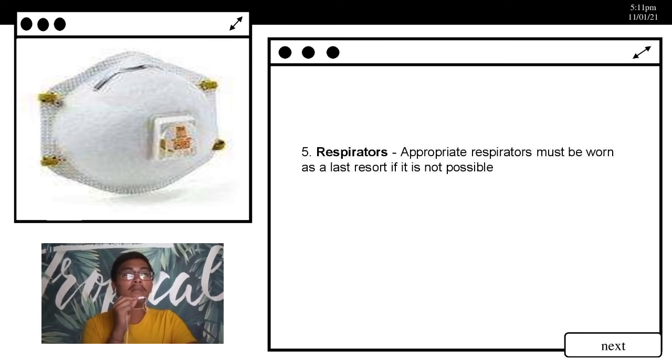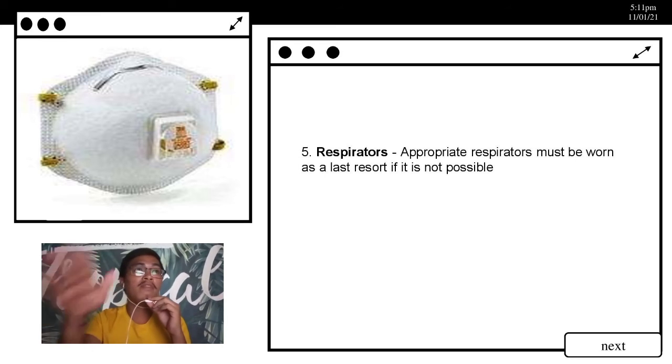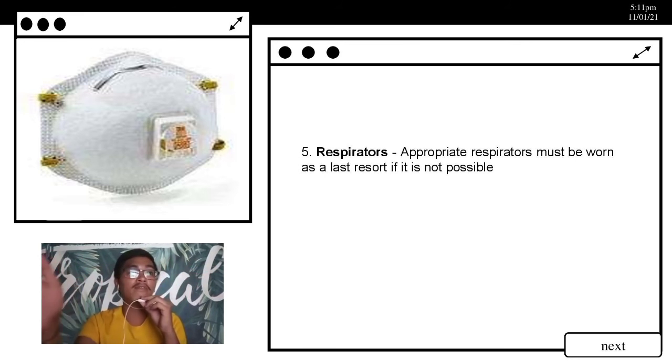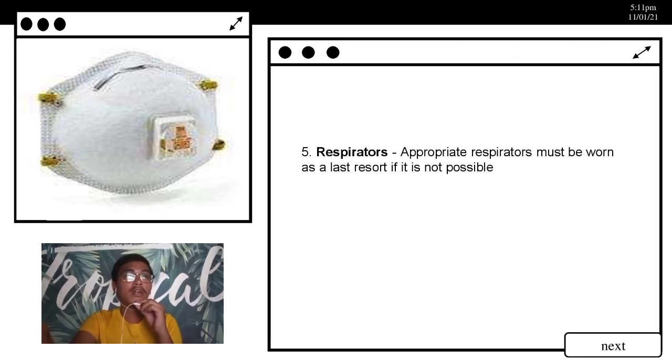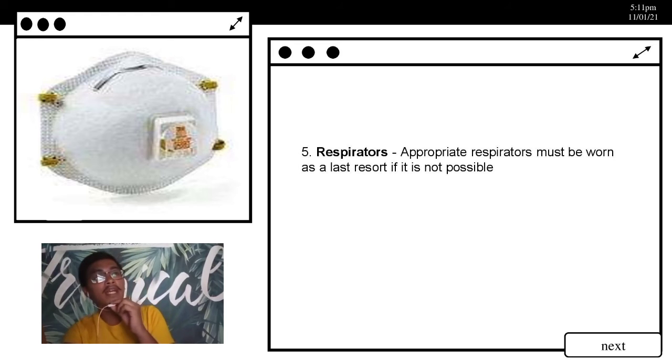You cannot use this without the half mask respirators or the full face respirators. So you have to, and before also you can have the half mask and the full face respirators, you also have these cartridges. It is only for dust and organic vapor for fumes or organic solvents only. Acid gas, vapors of hydrochloric acid, sulfuric acid, and etc.